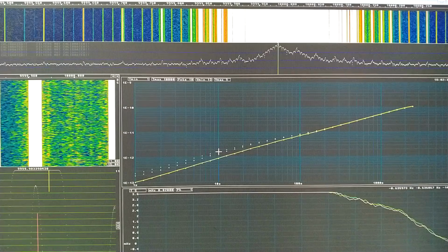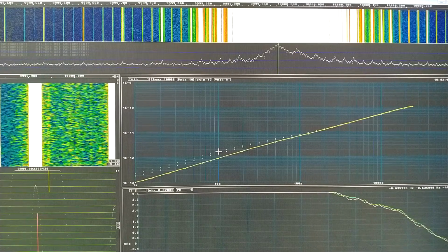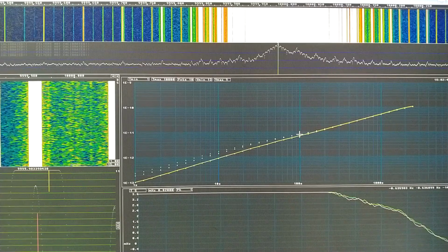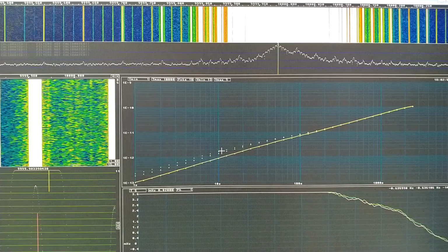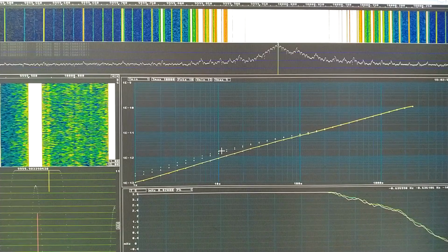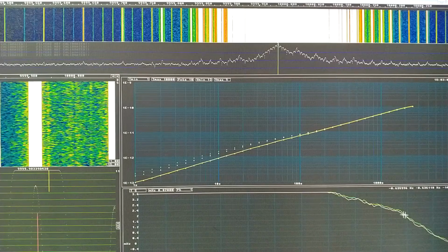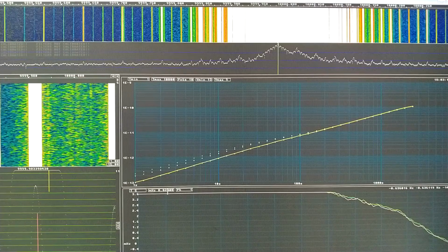I had some problems trying to make the time constant longer, so I did some modifications, and that made the time constant actually a little bit faster. So I need something like 4 times more time constant. I will try to see if that will give a stable locking. Frequency versus time looks very good here. The scale is 0.02 here, and the curves follow each other nicely.